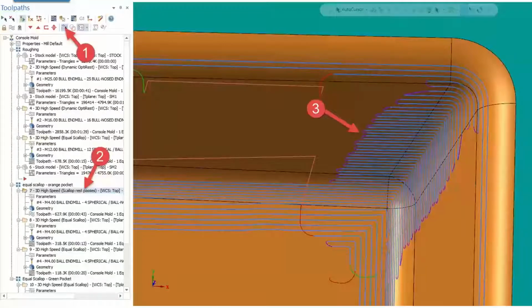And if that didn't get it all out, you would make another stock model, and so on and so forth, getting a smaller radius, smaller tool as you went along. The danger was if you went in too soon with too small of a tool, there's too much material there, and you risked breaking your tool, right?